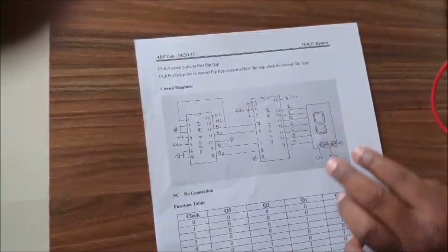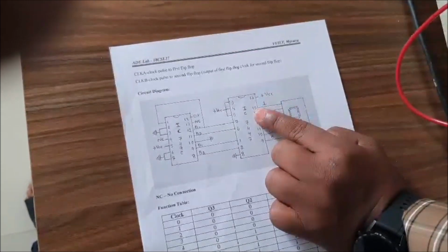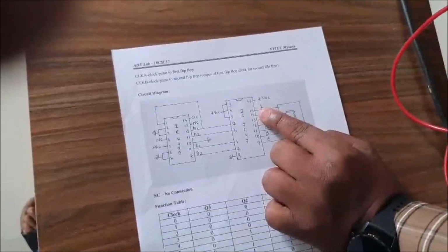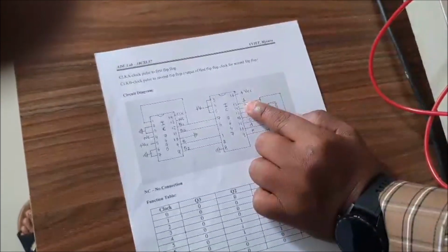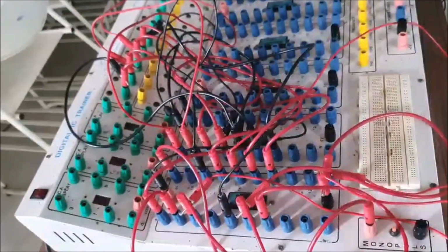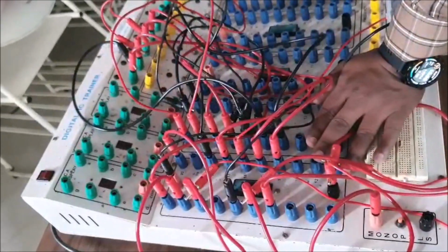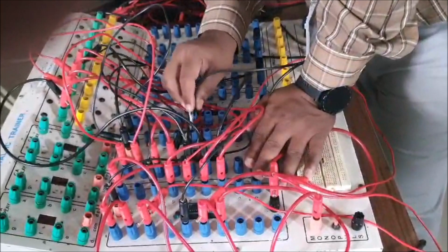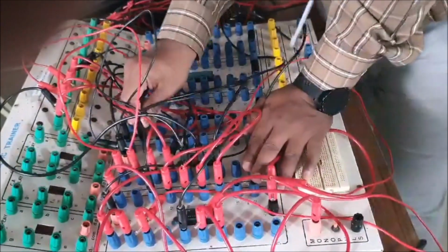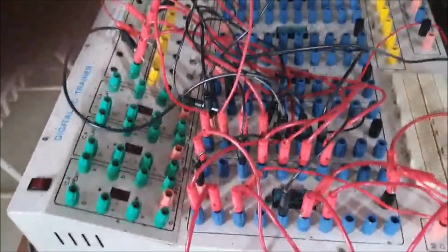Next, we need to do the connections for 7 segment display, where 15th pin, that is nothing but the F. 15th pin should be connected to F of 7 segment display. Now what I will do is, I will take one patch cord. One end is connected to 15th pin of 7447. So from the bottom right, the pin number starts from 9, then we have 10, 11, 12, 13, 14 and 15. I will connect one end to the 15. Another end of this patch cord is connected to F.